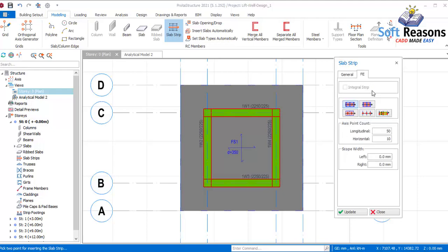Okay, come to the FE. We'll be considering this one. All right, this one. So we are going to be drawing it right away. Pick the first point here, move your cursor over to this other point with the control key to have a straight line, just like this.